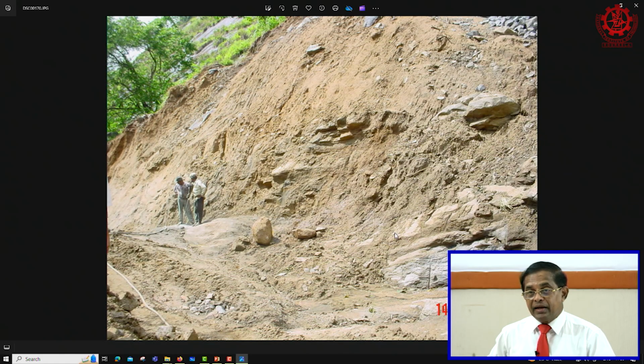Otherwise, it could have been a 10 megawatt project. So, we had to limit it to 4 megawatts because of the other environmental requirements. Remember these things also, there was a planned water project upstream, right. It was not implemented, but when we applied for the permission from the water board, they said we have a water scheme to be done in 10 years time and we want so many million liters a day. Therefore, we kept provision for that also, because our power plant is going to have a 30-40 year lifetime.